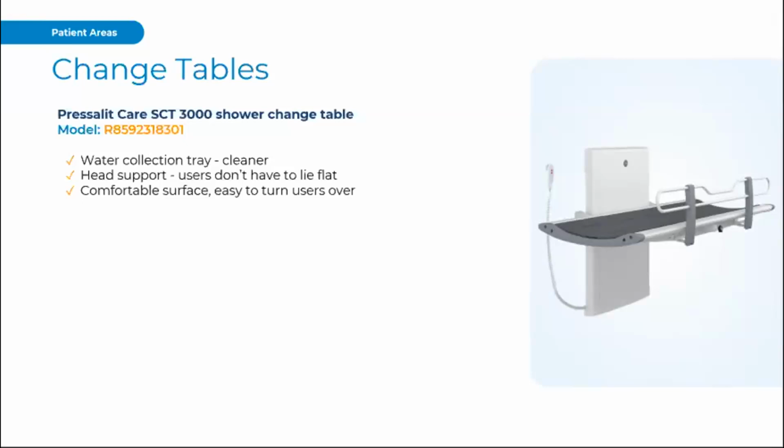For OBC, you're required to have a clear space not less than 810 millimeters wide and 1830 millimeters long in each universal washroom. They're adjustable height, required from 450 minimum to 900 maximum, and required to carry a minimum load of a specific kilonewton. Again, we can go through these in more detail.